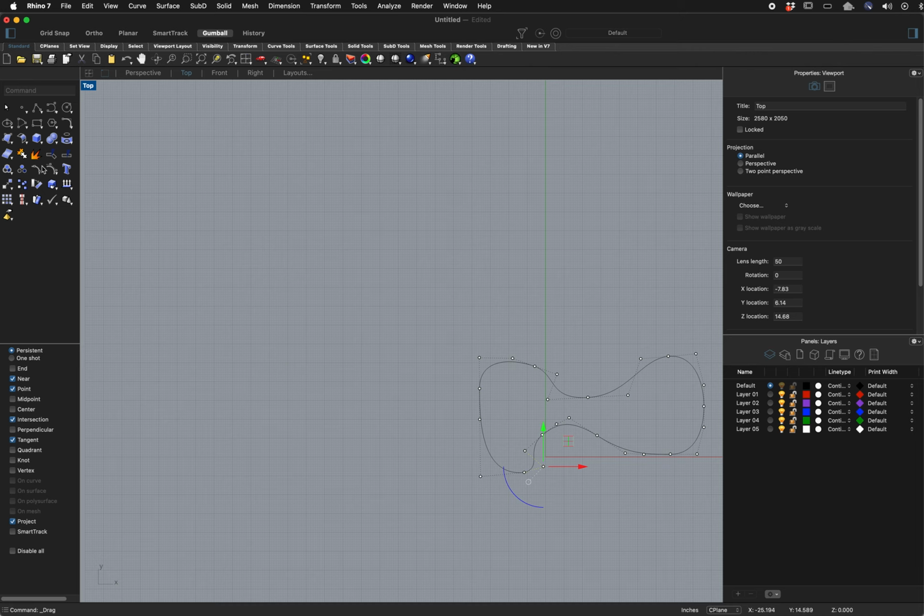Okay, so edit with the arrow tool. You can move the points around. You can adjust the handles. The one difference between Illustrator and this is that unless you select the Bezier handles at the same time, so select the control point, and then also select the handles, and then move those together, that's the only way you're going to maintain that curve. Otherwise, the control points will stay in the same spot. Okay, so that's the curve tool.